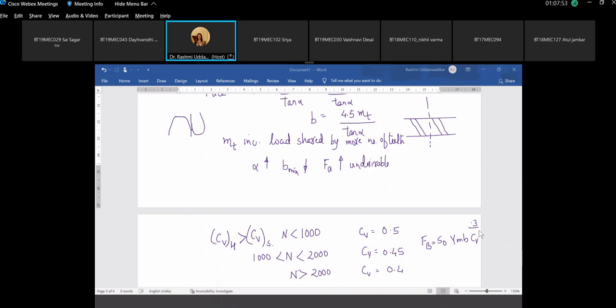Roll number 44, Ram, you are there? Due to smooth motion, less incremental load, so beam strength can be taken more, and so CV is more. As simple as this. Pradyuman is giving me the answer. And he says in one line, due to smooth motion in helical gears, less incremental load, and so the beam strength can be taken more than the spur gear equivalent.